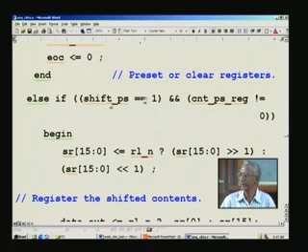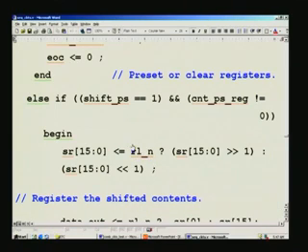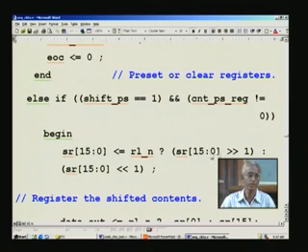For this condition we naturally have to do the shifting and output the result. So this is basically a mux to do that job based upon the right or left signal. Right means 1 here. If this signal is 1, then we do the right shift using the conventional statement, and then assign this back to itself here.